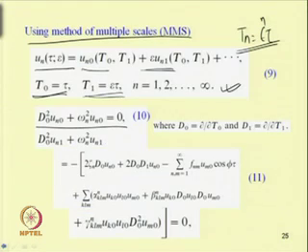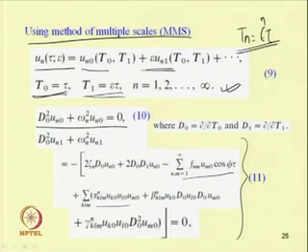Substituting this in the second equation, that is D0 square un1 plus omega n square un1 equal to minus 2 zeta n D0 un0 plus 2 D0 D1 un0 minus summation n, m equal to 1 to infinity fnm um0 cos phi tau plus the nonlinear terms. So, substituting that u term in this equation.